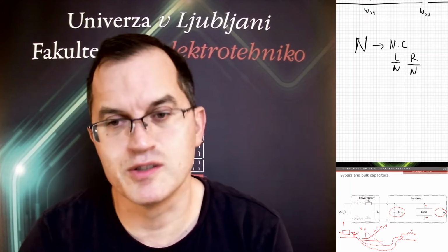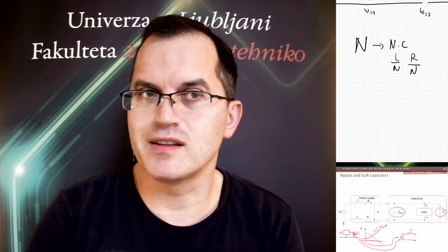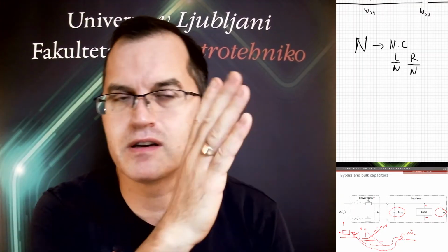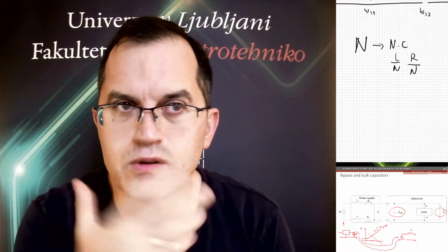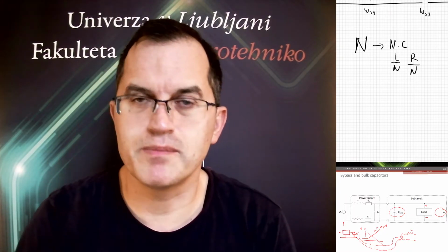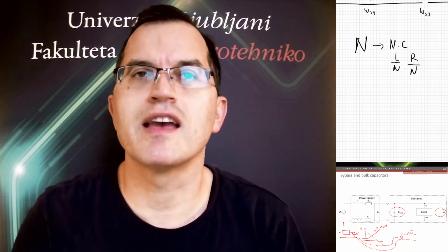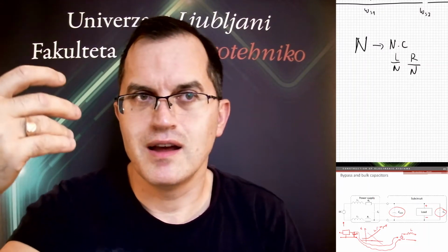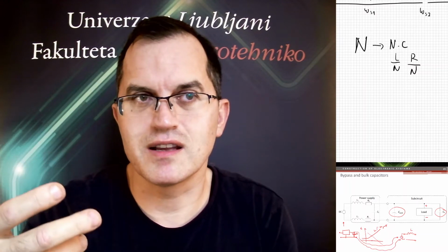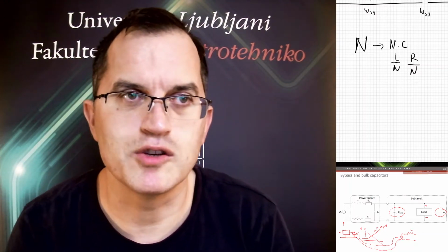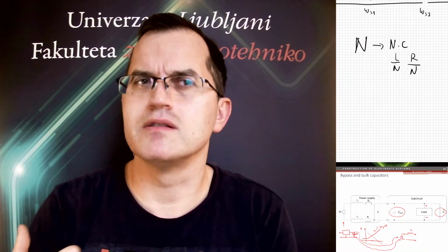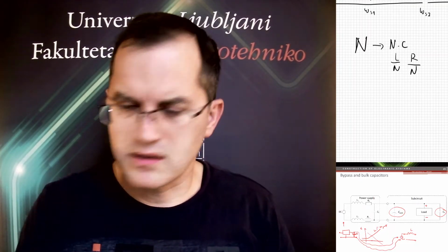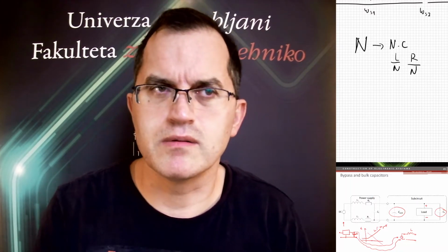Then if you apply this new capacitor, which has better quality, your resonance would shift a little bit further or lower, whatever. It would be more sharp. Maybe you would just hit one of the noise sources in your circuit and match it, and then you would have an EMC issue. And now imagine you are producing millions of these circuits, and they go into, let's say, cars. And now again, at a certain point, all these cars have problems with the EMC.